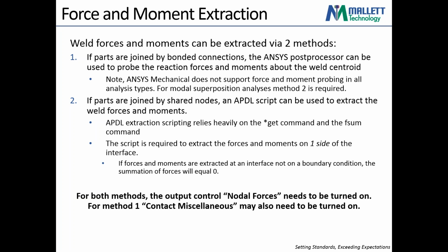And essentially what it does is, if we were to, at a junction, query the forces and moments at that junction and extract the forces and moments, by default we get 0 force and 0 moments, because let's say for a static structural analysis, our structure is going to be at static equilibrium, so there can be no residual forces in the body. What the script does essentially says, I want to extract the forces and moments on one side of the connection, right? And so that breaks out that piece, and so we no longer get a 0 force and moment result, and then we can use that to calculate weld stresses.